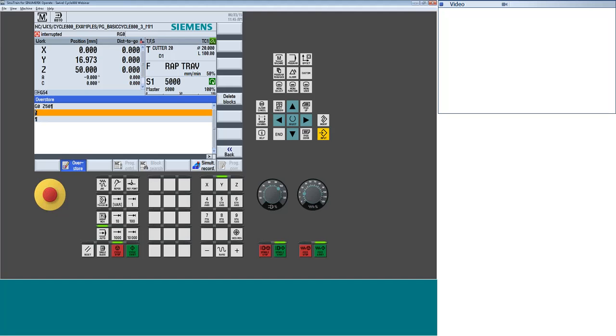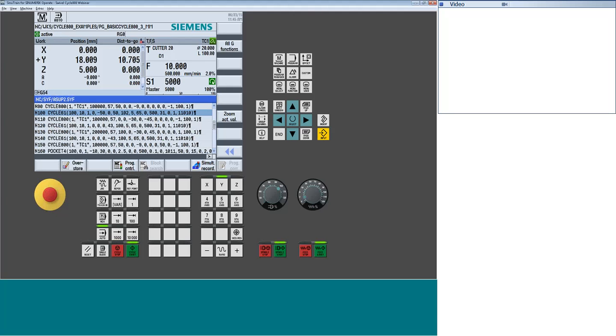So I can stage it, I can shut my spindle off, I can check some things, but when I come back out of Overstore, and I'll slow it down here, she'll do a reposition and then continue cutting where I was at. So it gets really handy, especially in 5-axis, a head machine, let's say, or a mixed lathe technology where I see you have some bars shoved in some side bore. I can do pullouts, and it's relative to all the offsets that are currently active or running.